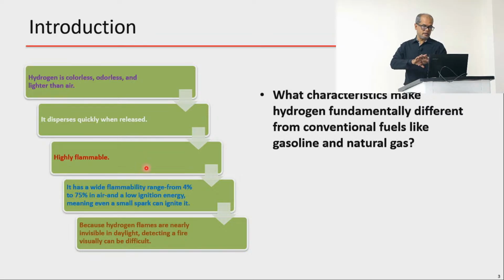It also has quite a wide flammability range, from 4% to 75% in air. And as I said, low ignition energy is required, meaning even a small spark can ignite it. And because hydrogen flames are nearly invisible, detecting a fire visually can be very difficult as well. So that's another aspect. We need to take safety very seriously when working with hydrogen, because it's not visible.